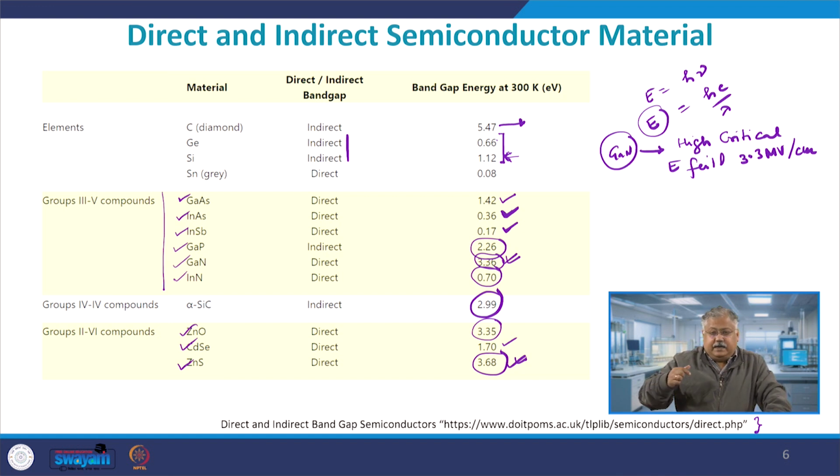So, basically it means that I can operate it at relatively higher voltages, and since the saturation velocity is larger, I can effectively apply a larger potential on the drain side and still not reach saturation. Every time I am trying to push this not only on the material side, but also the application side.